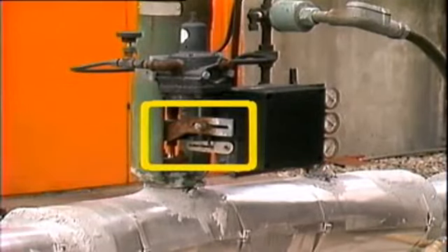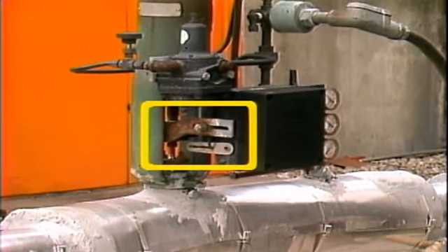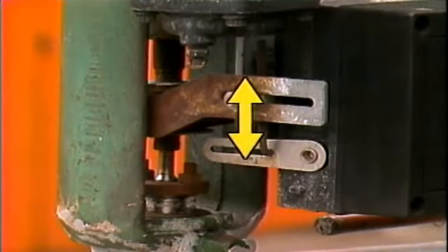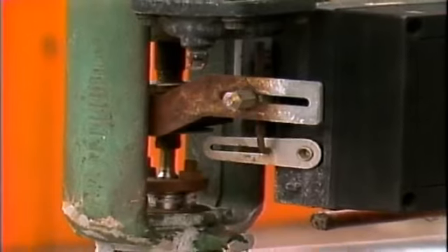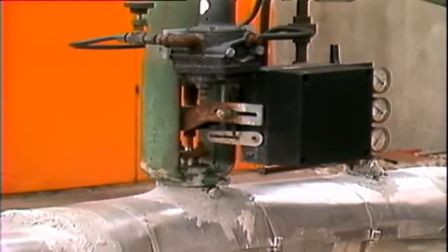A mechanical linkage joins the actuator stem to the positioner. This mechanical linkage may also be called a feedback linkage. As the actuator stem moves up or down, it also moves the linkage. The position of the linkage indicates to the positioner when enough movement has occurred to correspond with the air signal